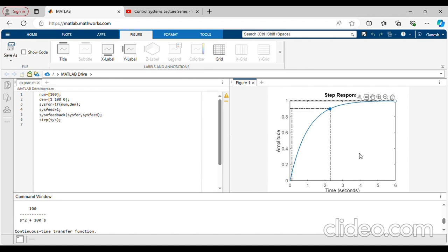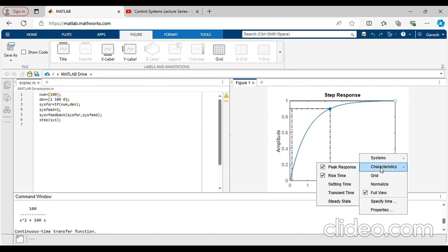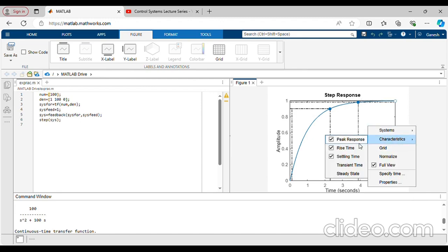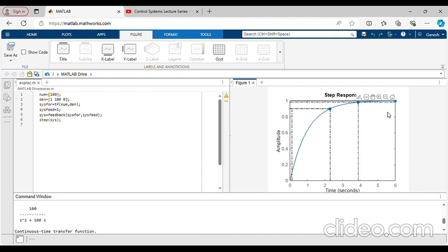Then what about the settling time? The settling time is 3.88 seconds. What about the final value? Again 1 only. So the steady state value is 1 only. These things were plotted separately from the MATLAB file into the Word file. So whatever I said, rise time 2.18 seconds, settling time 3.88 seconds, this is for the overdamped system. Now I am consolidating all these and putting in the inferences under the result.